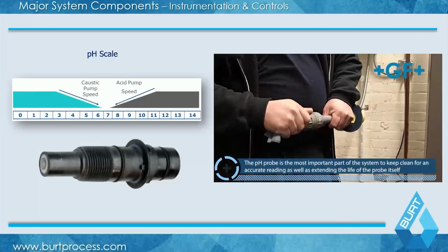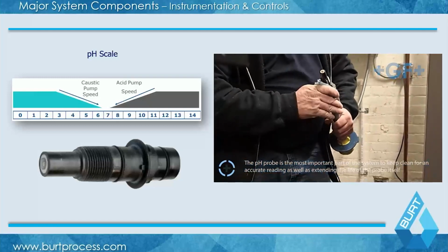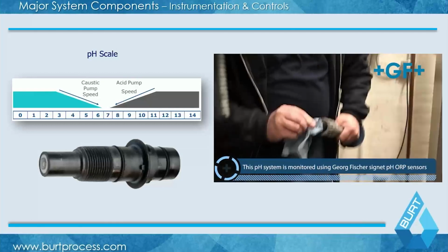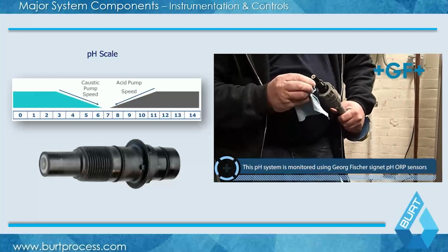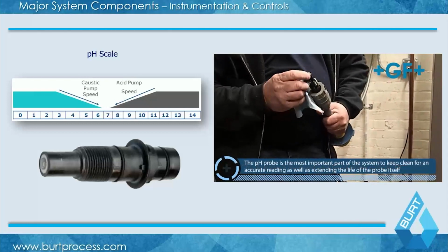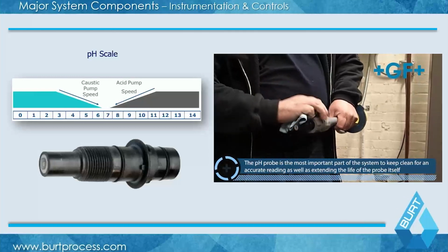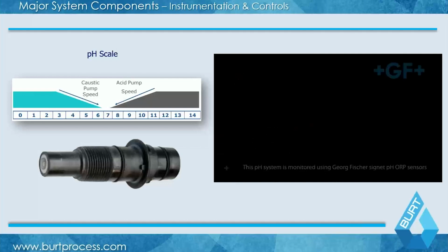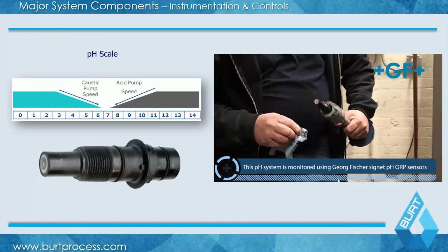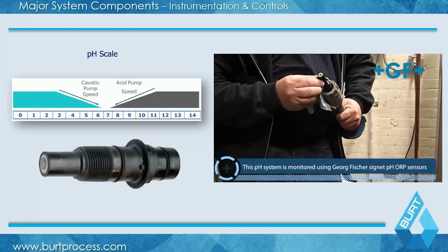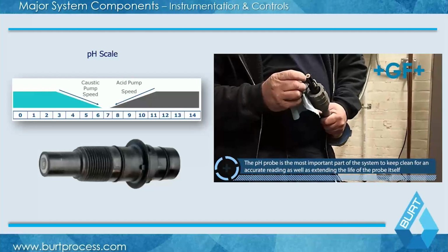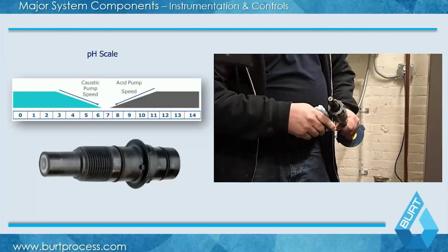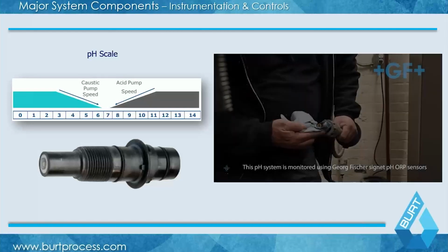The two most common chemicals used for reagents are 50% sulfuric acid and 25% caustic. There's a lot of variation. It's just important to know up front what chemicals you want to use in your system, to allow for chemical compatibility as well as proper control. Reagents in the system, whether they come in a drum or you use reagent tanks, need to be 110% double contained.